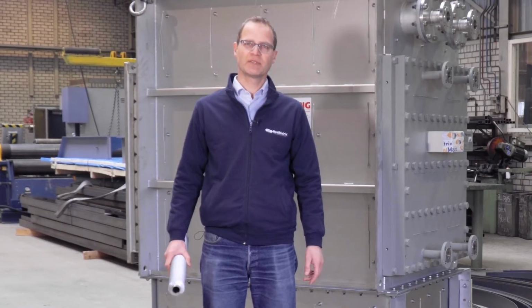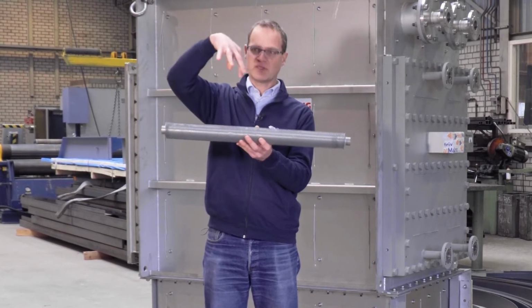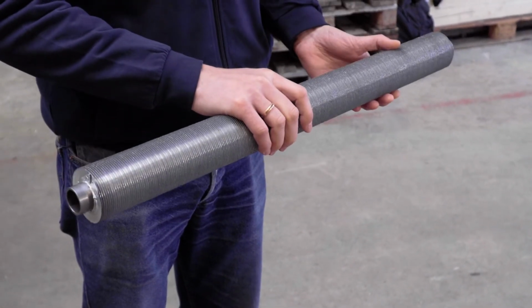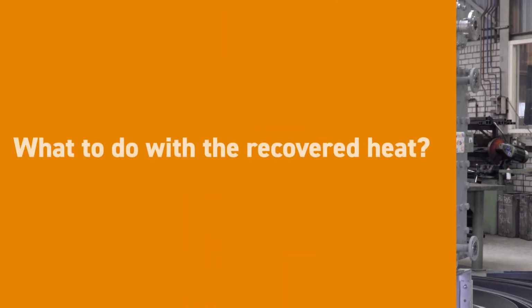An economizer recovers waste heat from flue gases. Tubes are installed in the flue gas stream. Flue gas flows around the tubes and inside the tubes cold water is flowing and is being heated up. So the heat is recovered from the flue gas into the water.